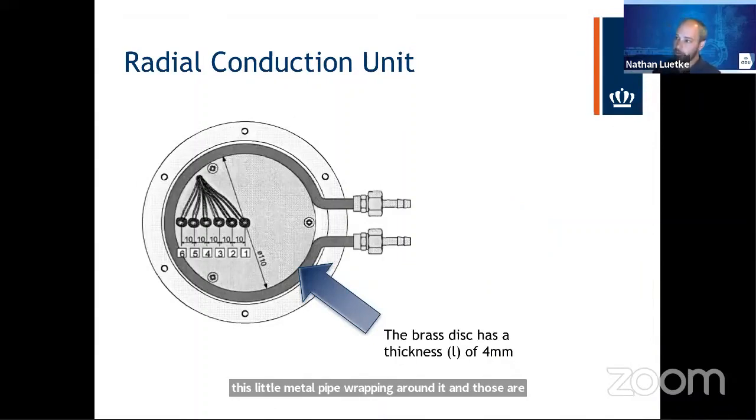There's a heater core resistor in the center that's receiving electrical power from the electric socket, turning into heat. And it's moving through the system because we have a temperature difference created by that cold water running through that outer wrap.